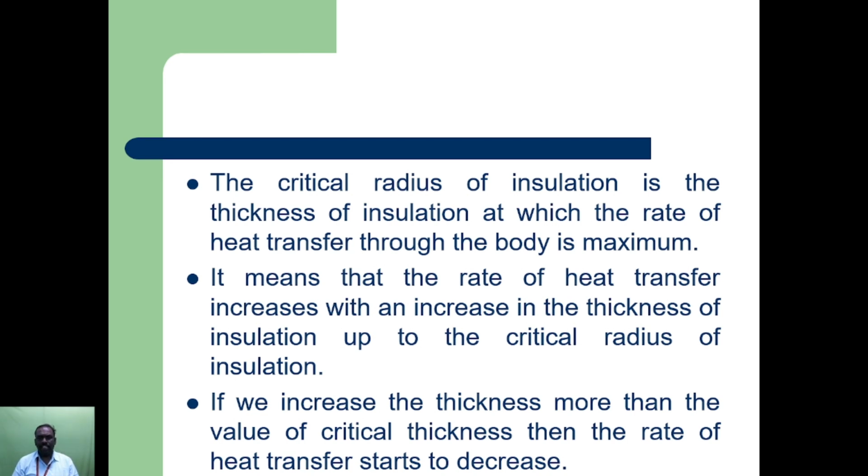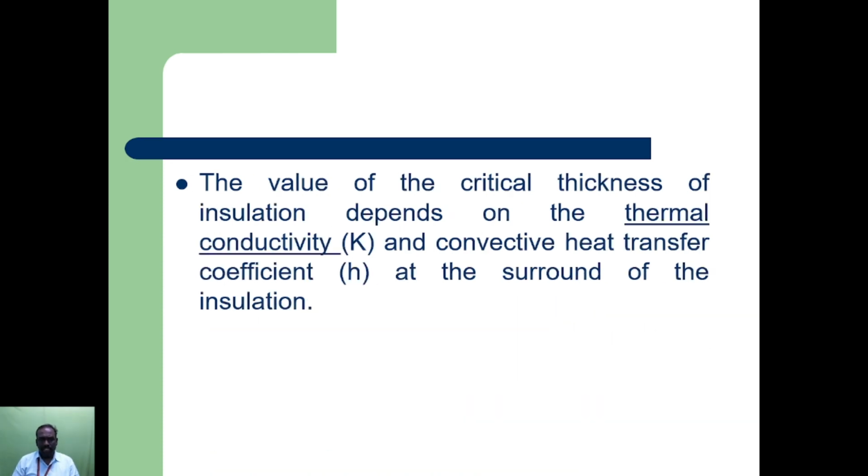The heat transfer increases with increasing thickness of insulation up to the critical radius of insulation. If we increase the thickness more than the critical thickness, heat transfer starts to decrease. The value of critical thickness depends on the thermal conductivity of the material and the convective heat transfer coefficient at the surrounding of the insulation, so it depends only on the conductivity and heat transfer coefficient.